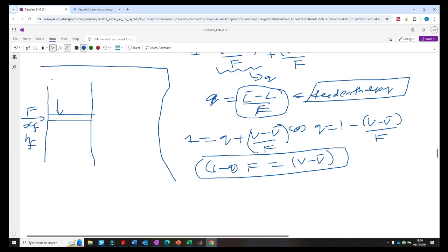So let's define. So L and then the corresponding mole fraction XL, and then the corresponding enthalpy is H suffix L, and the liquid that leaves the feed plate is L dash, and then the corresponding mole fraction is X suffix L dash, and then HL dash. Okay, so that's the enthalpy of the liquid stream that leaves the feed plate, and then the vapor stream that enters the feed plate is V dash, and the corresponding mole fraction is YV dash, sorry, and the enthalpy is HV dash.